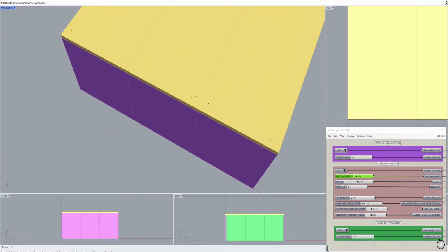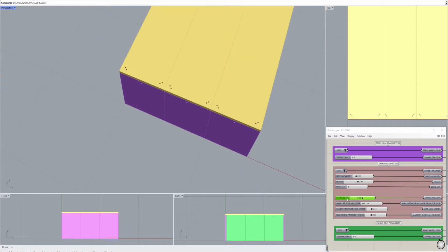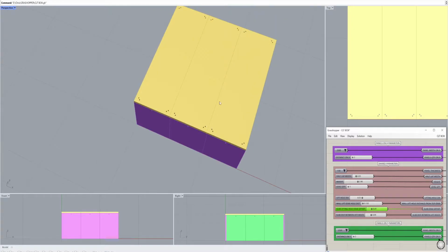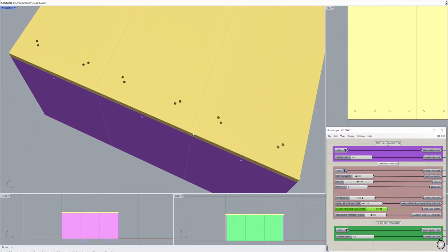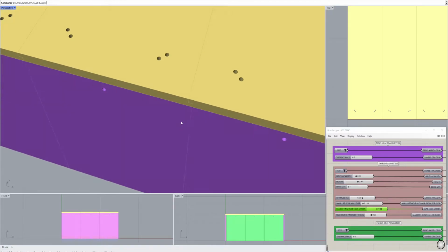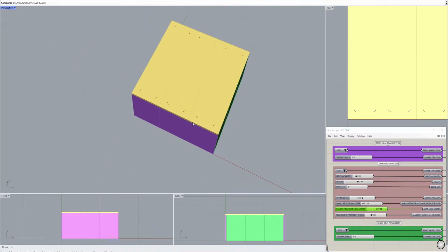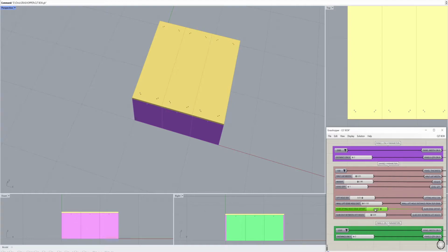So if we change the lifting hole to, let's say, 30 millimeters, and here we got the slab lifting hole from the edge offset. So this is like an offset of the slab profile, and there we go. See how that moves? You can move it in. This is all based off of the internal center of mass. So again, a rectangle is pretty easy. It's going to be more or less the center. But you can see there's a slight offset. That's because it's accounting for the half lap. Well, that's what I would assume it's doing. So we have that there.